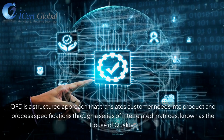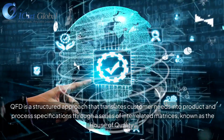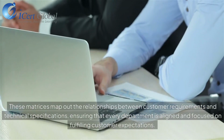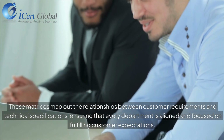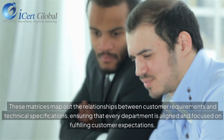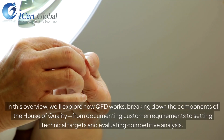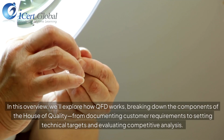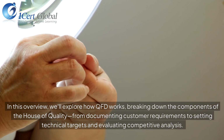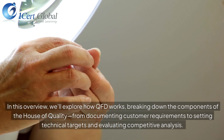QFD is a structured approach that translates customer needs into product and process specifications through a series of interrelated matrices, known as the House of Quality. These matrices map out the relationships between customer requirements and technical specifications, ensuring that every department is aligned and focused on fulfilling customer expectations. In this overview, we'll explore how QFD works, breaking down the components of the House of Quality, from documenting customer requirements to setting technical targets and evaluating competitive analysis.